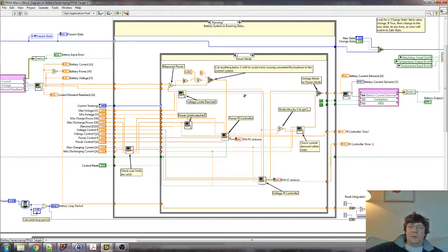So we end up using this voltage limit path, where we have a voltage PI controller just the same as the voltage loop. And we need to tell the controller that this is the voltage limit path that we're interested in. This pathway is always processing the input data, so it's always making a control decision. It's just a question of whether that control decision is allowed to propagate. Similarly, if we're in the situation where the power limit's been reached, so that's because the voltage is fine, but the current is such that the VI product is now greater than the power limit.